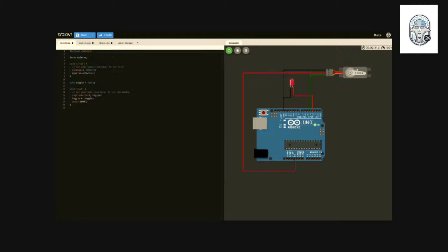All right, so the servo does nothing. It went to a neutral position, but that's just the simulator doing it. But what we can do now is that here we can say myServo and write to it. Say 180. And this will change the position of the servo. However, it's always going to change it to the same position. So this was just checking that we get everything right. So it moves to the 180-degree position.